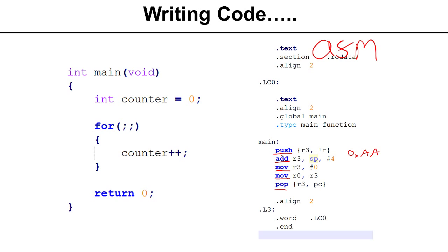So assembly code is a little bit higher-level way of writing down the instructions for that core in a way that humans can understand. At one time, you actually wrote in hex or in binary, but the first tool that was made was what's called an assembler that does some of that work for you. It makes it easier to read. You can put in nice labels. You can put in other directives to where you want to align data, and where you want to put your code. But you're at a very, very low level.